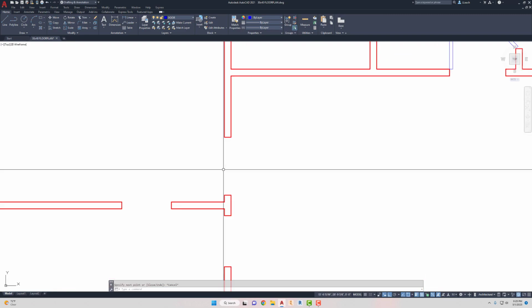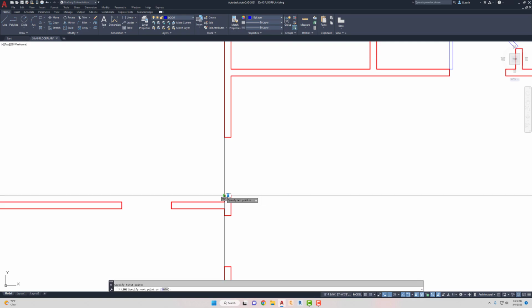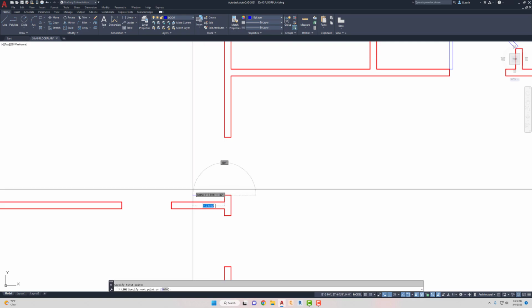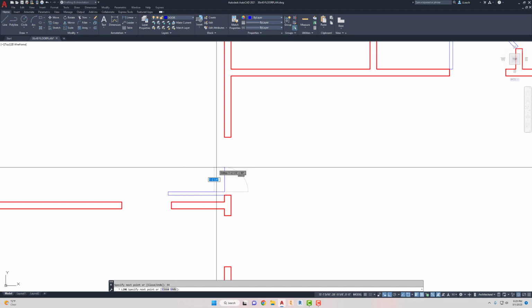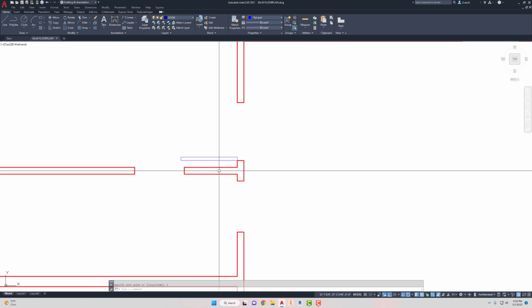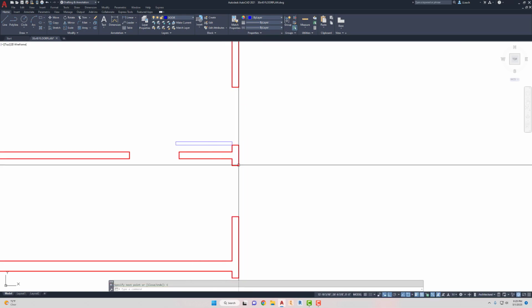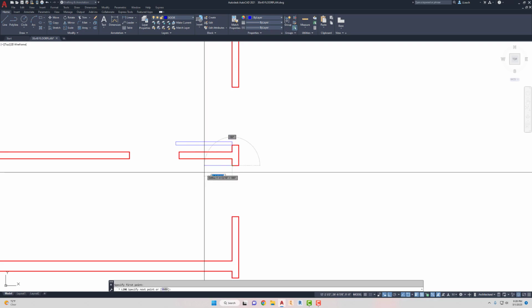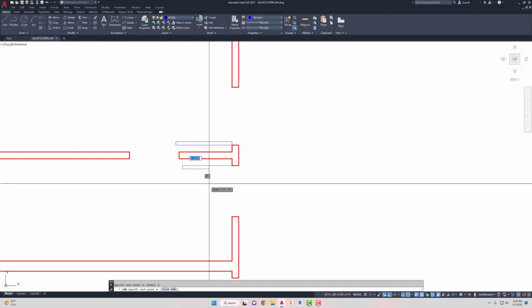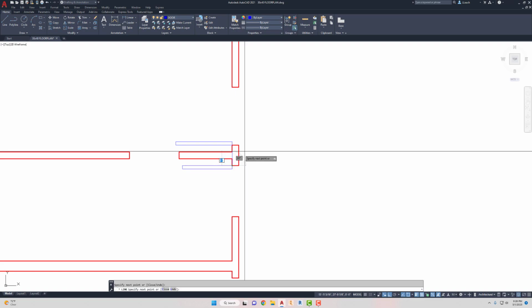This bedroom door, we made that 2'10", right? Which is 24 plus 10, 34, yeah. 34, up 2, over 34. There's that. Let me skip that little pocket door for now. This one is going to be from here over 30, down 2, over 30. And just close it where we started.